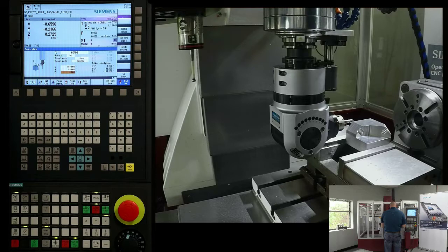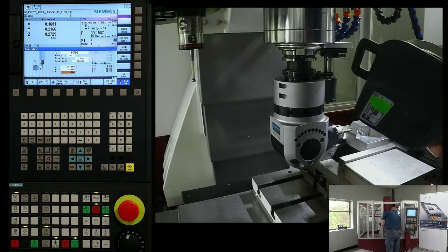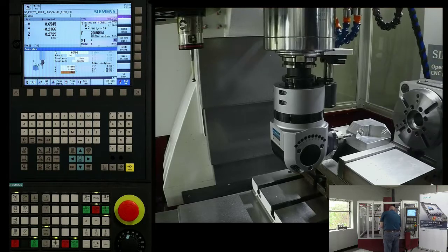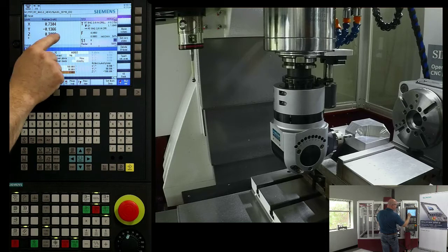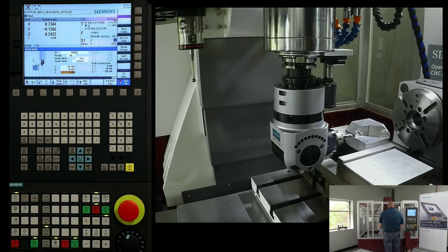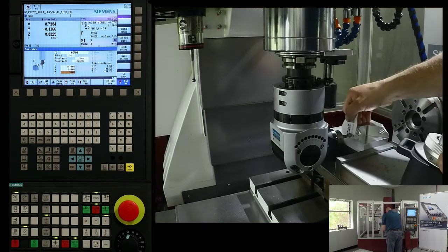Sometimes it's easier as an operator to not think about how the machine's been tipped around, but only think about my physical axes, right? That's what I'm doing right now. As I crank the Z-axis, I get a Z-axis move. If you look at the display, I'm actually getting the Z moving when I crank X because my coordinate system has been tipped by this cycle.